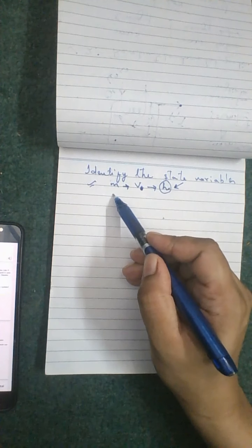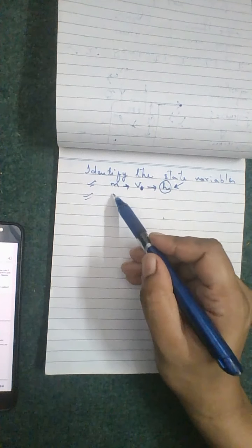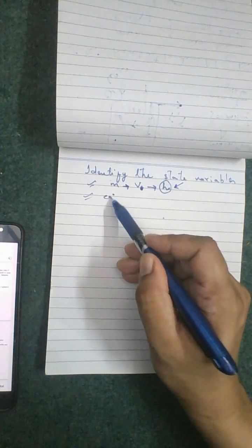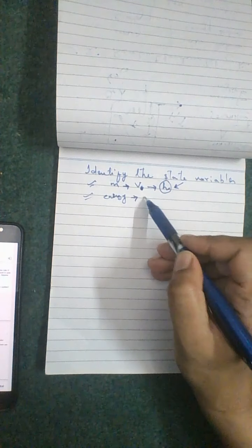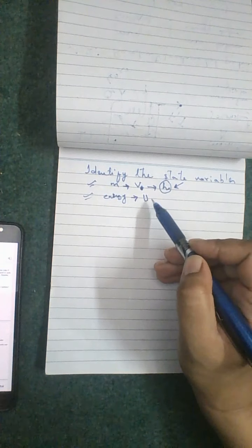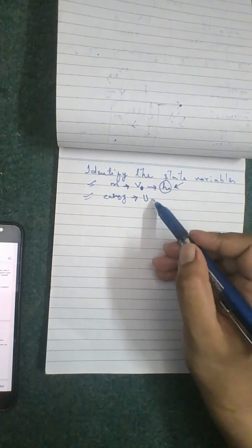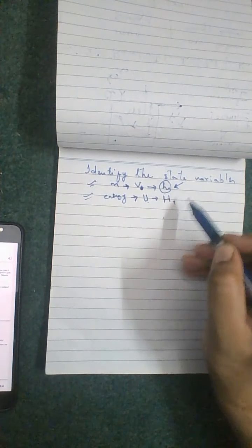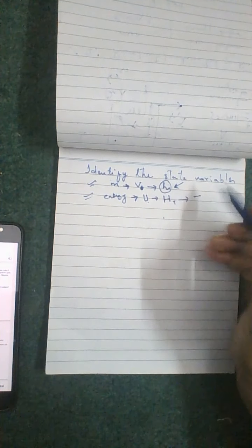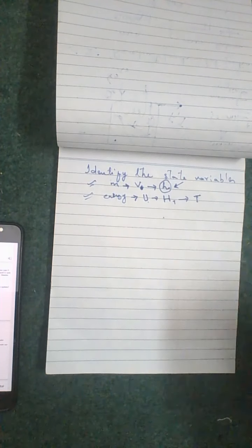Now looking at the second fundamental quantity, as I have said, energy is changing, accumulating because of the heater. This means internal energy is changing because kinetic and potential energy are 0, and this internal energy is related to the total enthalpy, and this total enthalpy is then related to the temperature.